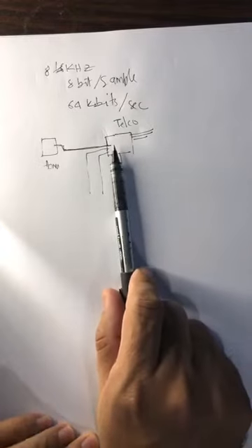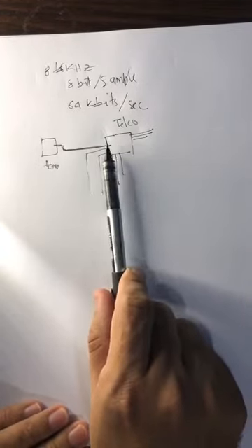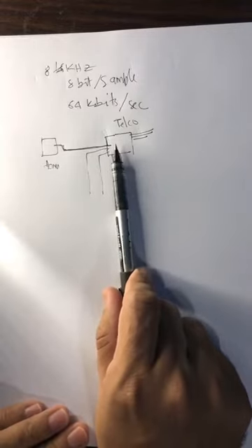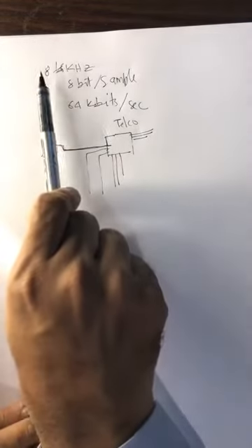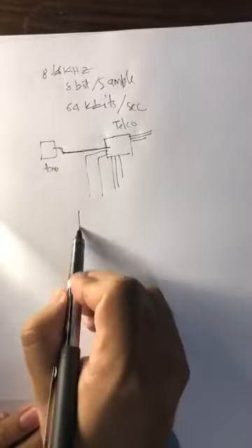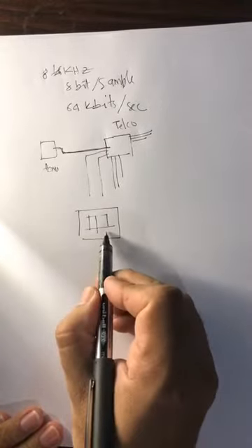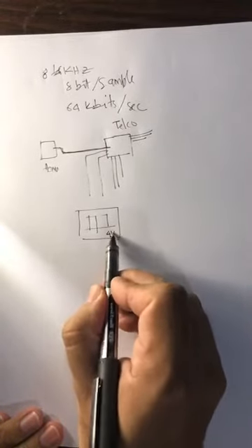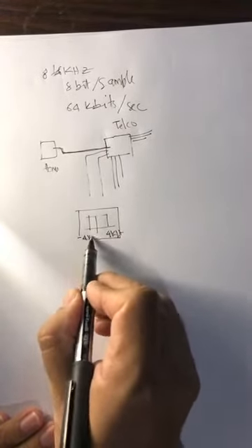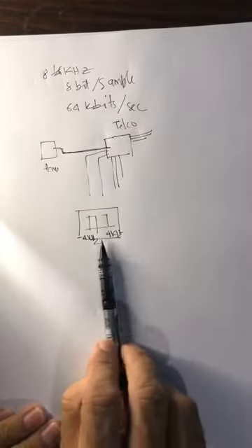And the first thing the telco would do is that it will sample every voice at 8 kilohertz. So 8 kilohertz means first they will pass it through a low pass filter, which is a 4 kilohertz filter, to make sure that nothing goes beyond 4 kilohertz to an A to D converter, which is sampling at 8 kilohertz.